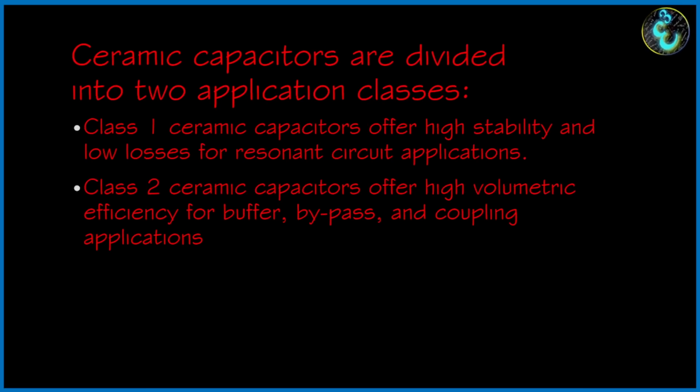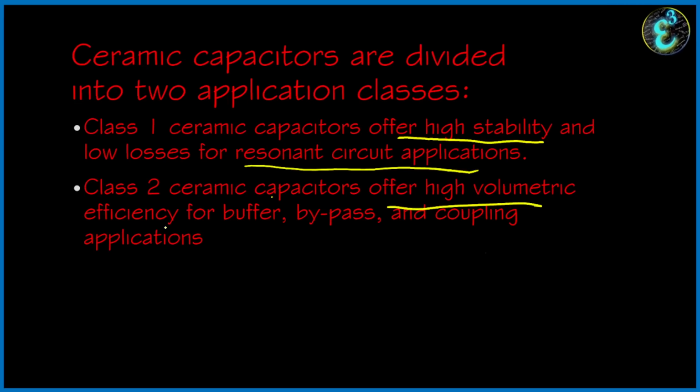Class 1 offers high stability and low losses, so this is for resonant circuit applications, while Class 2 offers high volumetric efficiency and is for bypass and coupling applications.